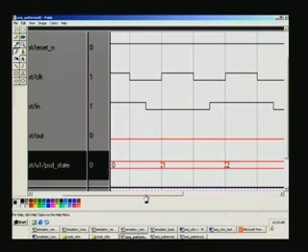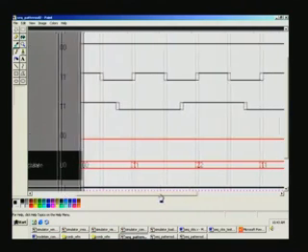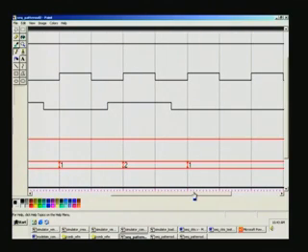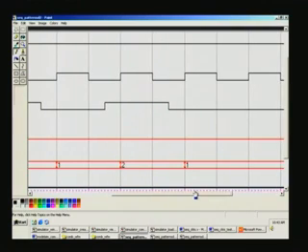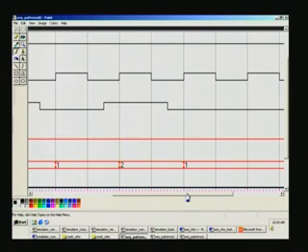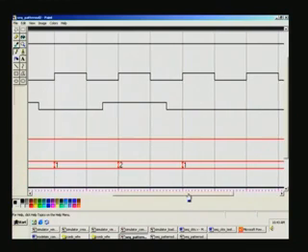The state. I mean, this state. Yeah, state is the first thing that will happen, right. In state machine we have already seen the output is dependent upon the actual state. So, unless you go into that state, there is no question of that particular output being effective, right. So, it will take place only at the following clock pulse. So, that is what happens here. So, is this okay? Transition from 2 to 1, and that is what we have seen. Yes.